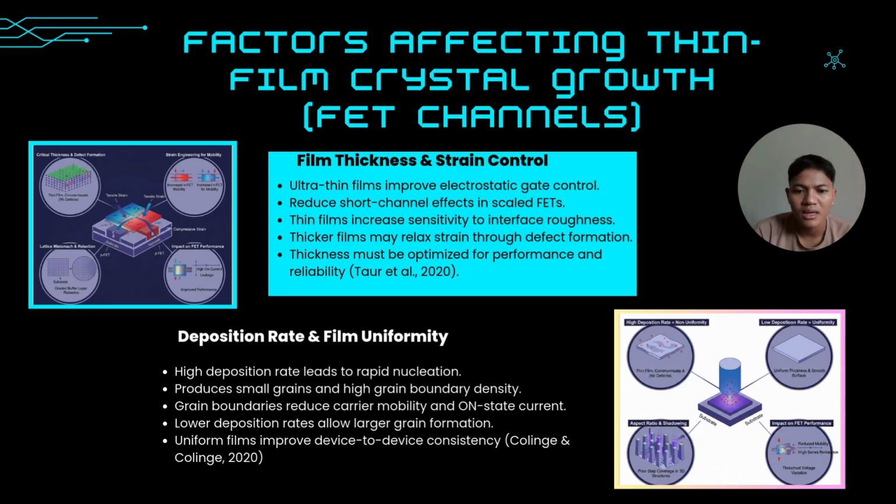Next is film thickness and strain control. Ultra-thin films improve electrostatic gate control and reduce short-channel effects in scaled FETs. Thin films increase sensitivity to interface roughness. Thicker films may relax strain through defect formation. Thickness must be optimized for performance and reliability, based on Tour et al. 2020.